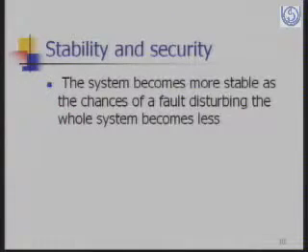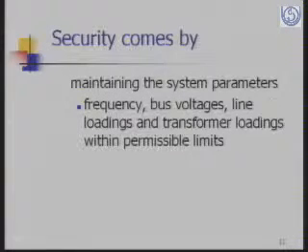Then stability and security. The system becomes more stable as the chances of a fault disturbing the whole system become less. Security comes by maintaining the system parameters like frequency, bus voltages, line loadings, and transformer loadings within the permissible limits.